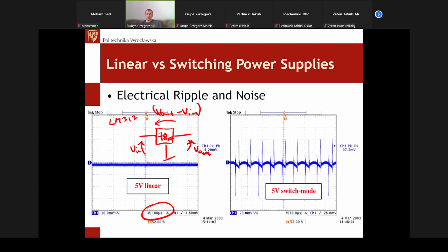Low dropouts are widely available, so there is no problem of availability. They are, of course, more expensive than the standard solution because they are better. But in single units, if you build some small short series, that's not a problem. So the pricing is not an issue. So generally, we should avoid using standard regulators. Rather, in my opinion, we should use low dropouts by default. Low dropout is simply better than, only more expensive than, a standard regulator. But that's problem number one.